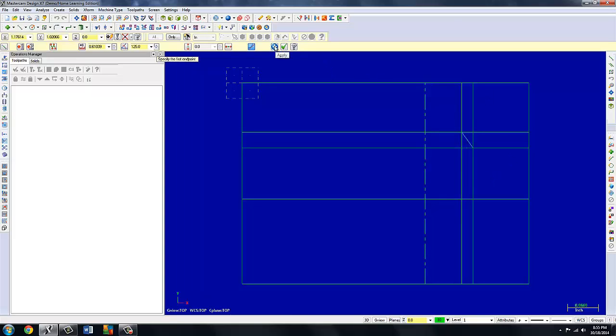I can also work on the 45-degree. I apply that. The 45 is actually 45. Enter. It originates right at this intersection, and my 45 went away. I'll have to lock it back in there. I'll drop it in near the top and apply that. I'm also going to put in the horizontal line that this cuts off at.